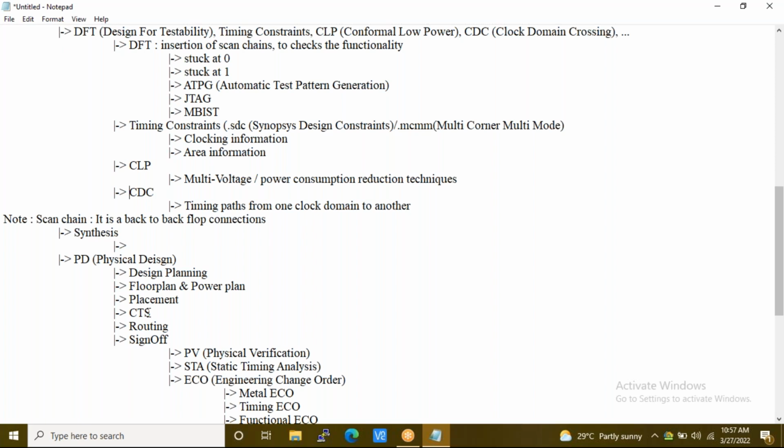Now all these components are interconnected with each other. That means the processor is connected to the keyboard, and an address signal is moving from the processor subsystem to the USB subsystem. So that means it is changing from one clock domain to another clock domain.